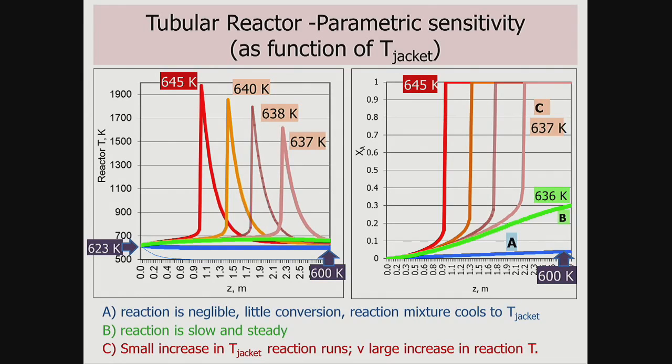So it's safe. We've operated, it's safe, and we've got a little bit of conversion. But obviously, it's not what we want. So we're going to increase the temperature a little bit. We're going to try not to cool it quite as efficiently. So we're going to let the bed temperature rise, the green line, by reducing the cooling slightly. And the green line is sort of nice. It seems to do its job. It levels off, and then it seems to be stable. The conversion's good. We've gone from about 5% conversion to 30% conversion, so that looks okay.